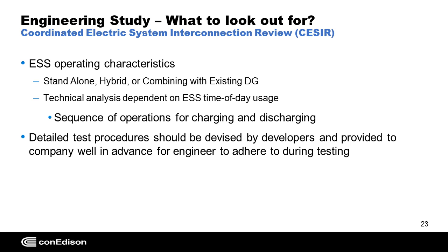One other thing to be aware of, and this really applies for all DG: we request that the test procedures be devised by the customer or developer and provided to the company well in advance. That really helps the engineer. It gets everybody on the same page. It shows how the engineer will test certain functionality of the inverters and the storage system, and how it works out on the site. It also lets the customer or developer understand those exact steps, so they know exactly, when the engineer gets to site, what steps to follow, what the protocol is, and what would be looked for after each step.